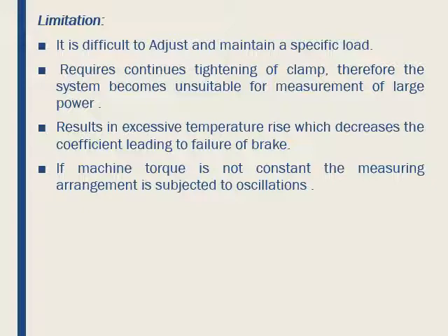Advantages: it is simple in construction and much less costly. They are suitable for the measurement of small power. Disadvantages: the coefficient of friction is reduced due to the wearing out of the block. Hence, in the long run, such dynamometers become unserviceable for the measurement of large powers.